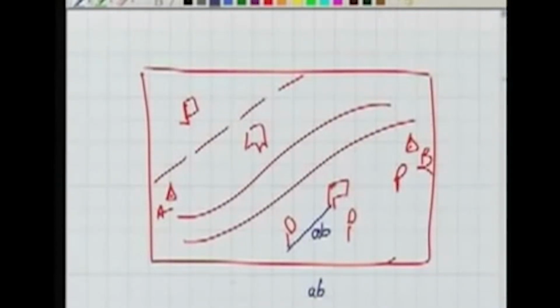We have the same distance on the ground, let's say I am writing it as capital AB. Don't confuse it with the small ab. It's the distance between those two objects. On the ground, I compare it with the small ab multiplied by the scale. Ideally, these two should be the same.